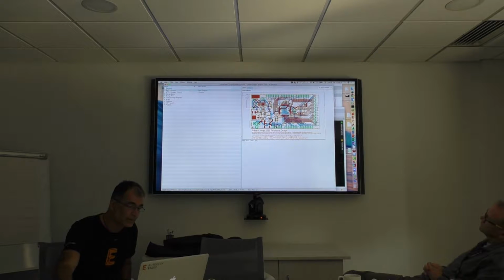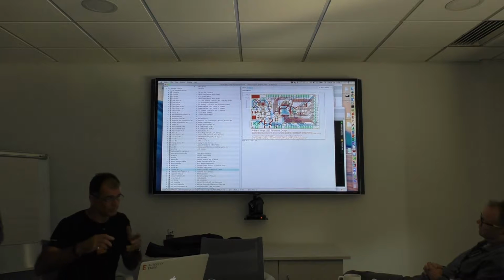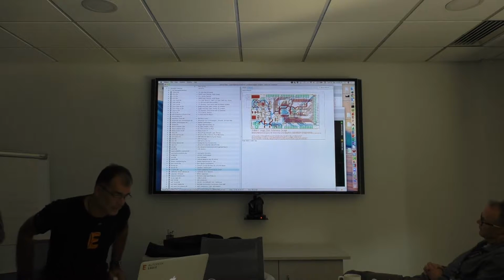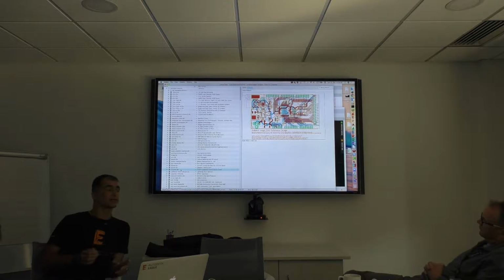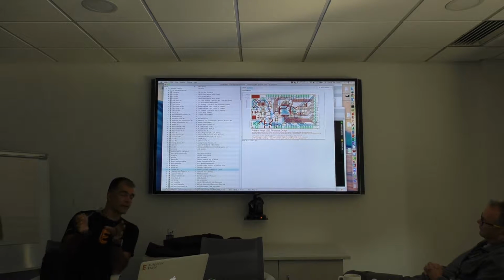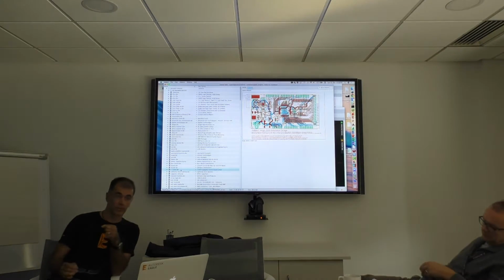And if you go into the Managed Libraries folder, you see a list of library names. That's basically a file which is behind this all, and these libraries are managed. So they come with the Eagle package. You have it on your computer, but there is also a platform we call library.io. You can access it as soon as you have an Eagle account. You can also log in to library.io.